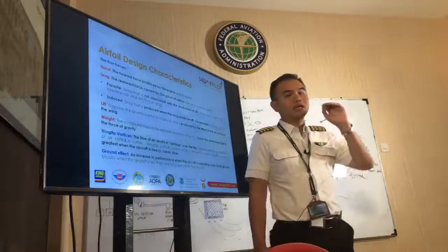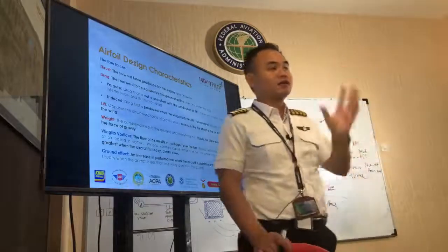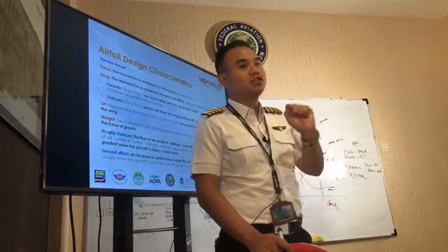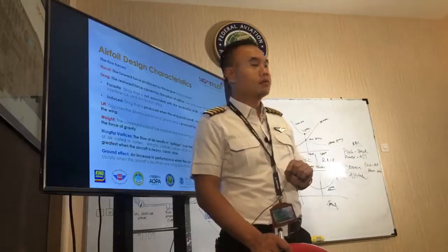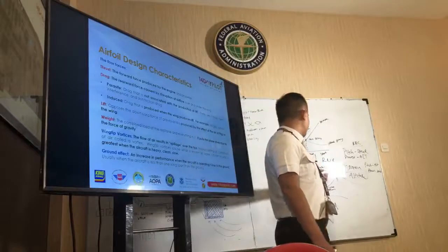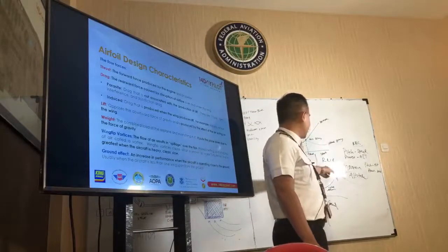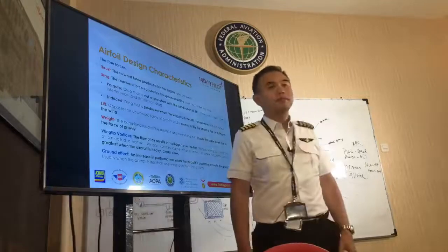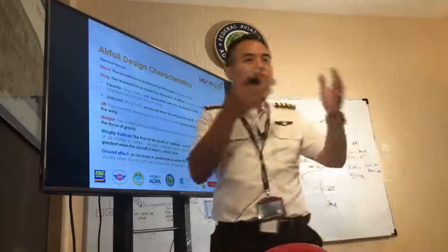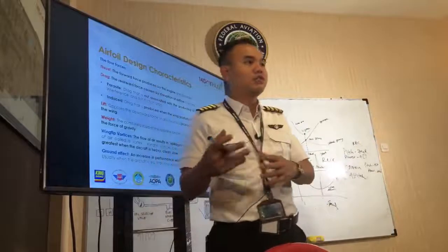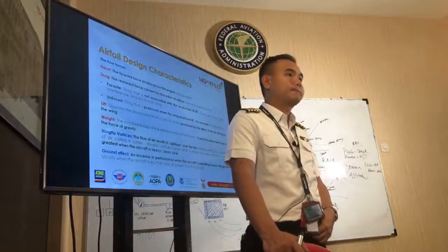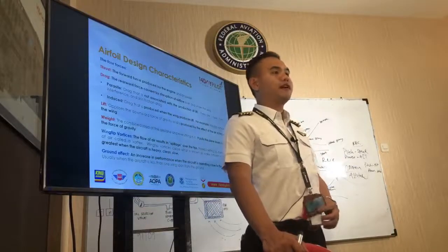What we care about is when we have an engine failure, the first thing is to pitch for the best glide speed. The total drag becomes a function of the power and the airspeed. You get that intersection. You know that there's a region of reverse command, and you also know there's a region of normal command. But in a Cessna 172, 65.